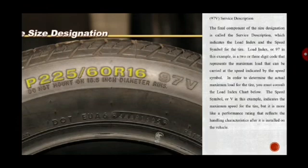Next, 97V is the service description. The final component of the size designation is called the service description, which indicates the load index and the speed symbol for the tire. Load index, or 97 in this example, is a two or three-digit code that represents the maximum load that can be carried at the speed indicated by the speed symbol.